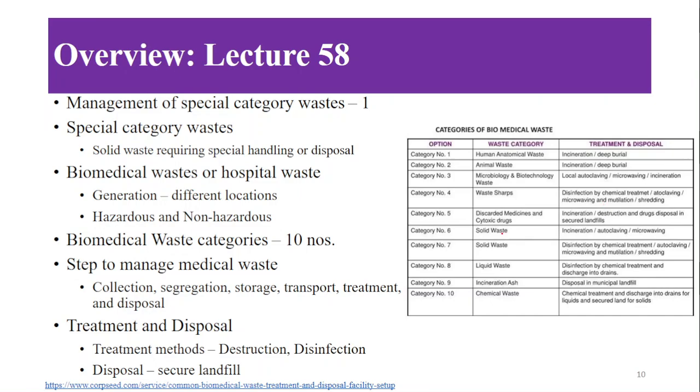The solid wastes are incinerated, autoclaved, or microwaved. Next, another category, solid waste, can be disinfected by chemical treatment, autoclaving, microwaving, and mutilation, and then shredding. The liquid waste is firstly disinfected by chemical treatment and then discharged into drains. The incineration ash is disposed in the municipal landfills, and the chemical waste is treated by chemicals and then discharged into drains for liquids and secured land for solids.